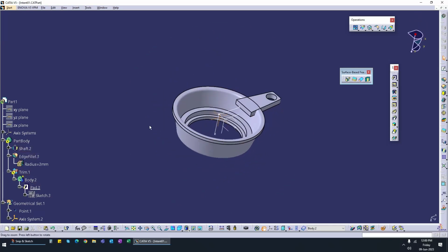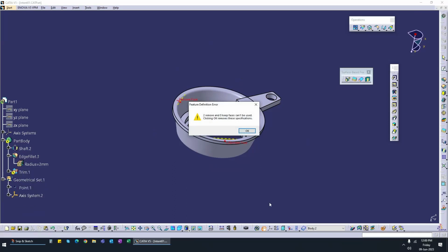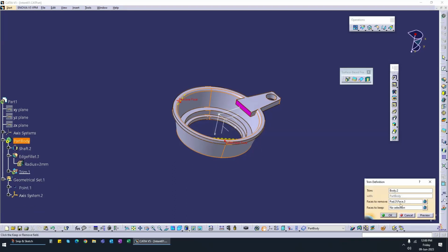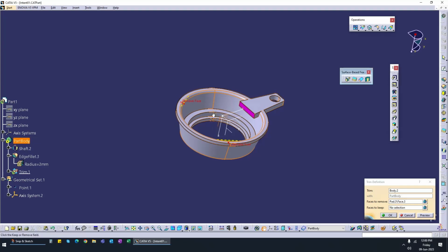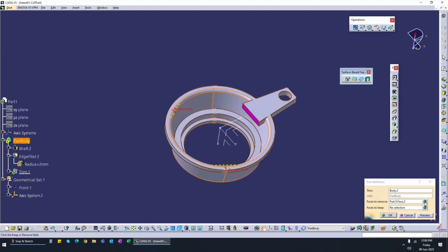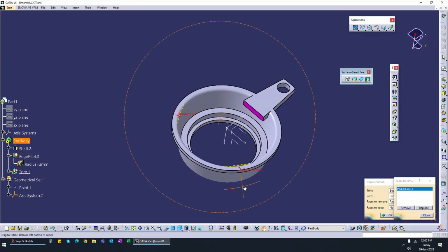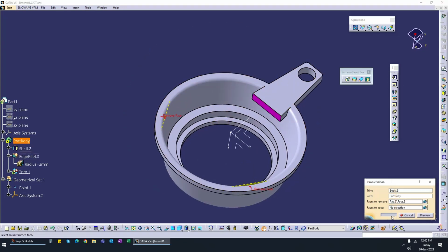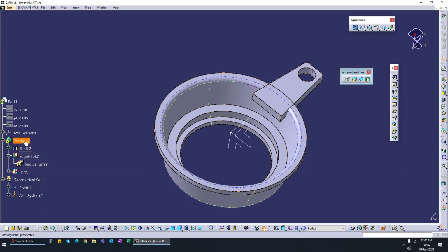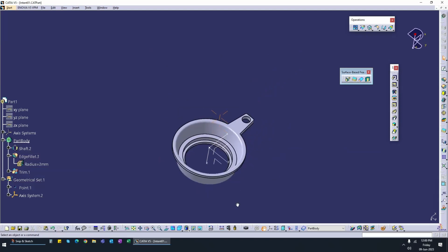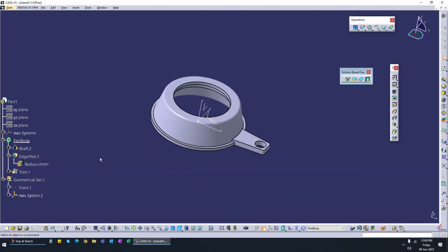And to overcome this problem, we can just simply go to trim, and open this option. We select the only one face that we have, and we click OK. Now we define our main part, we do an update, and we have our tab, but we still want those two other tabs with the required length.